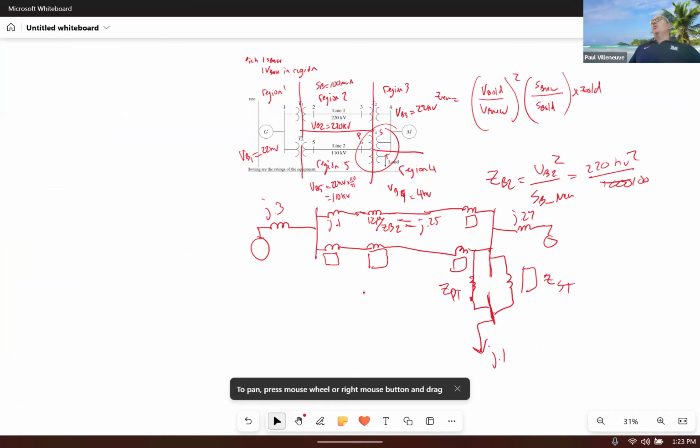You will notice I did not show that as a capacitor. I showed it as an arrow. So when you're trying to differentiate between an actual load that's a power load or an actual load that's an impedance, if it's an impedance, you show it as a circuit element, resistor, inductor, capacitor. If it's an actual power load, you would use the arrow to indicate what's going on.